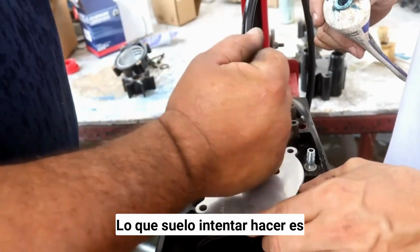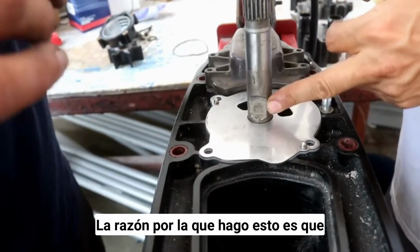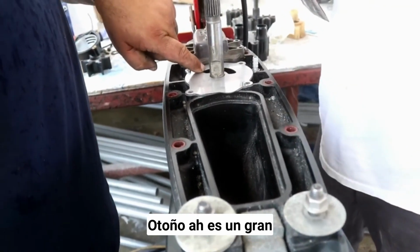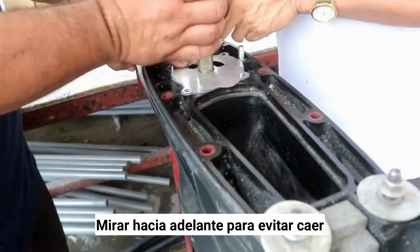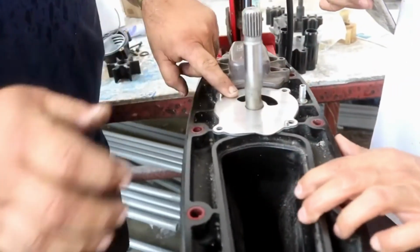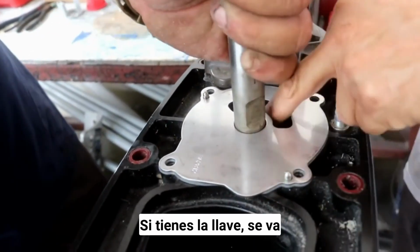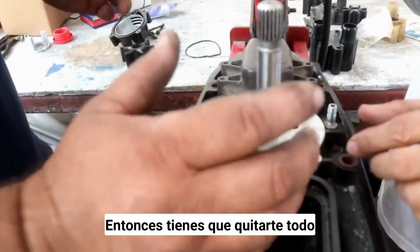I normally try to have the keyway pointing this way. The reason I do that is if you drop the key, it doesn't accidentally fall. That's a great tip. Facing forward avoids dropping the key over there, because if the key goes into the hole, that's not good. Then you'll have to take everything back apart.